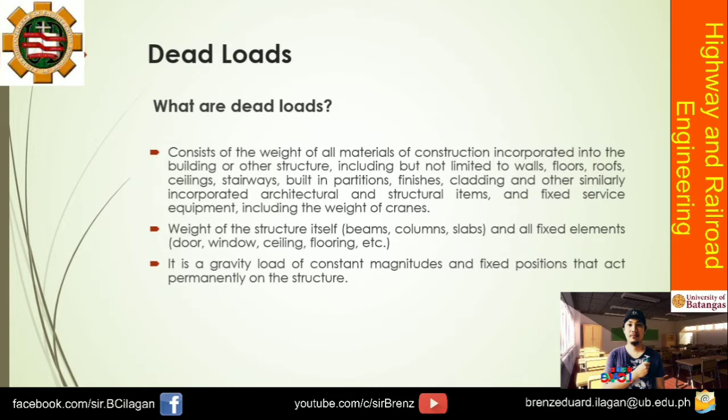So, consists of the weight of all materials of construction incorporated into the building or other structure. So, lahat ng mga bagay or materials na ilalagay mo doon sa structure, you need to compute the dead load or the corresponding load of that material, including but not limited to walls, floors, roofs, ceiling, stairway, built-in partition, finishes, cladding, and other similarly incorporated architectural and structural items, and fixed service equipment including the weight of cranes.